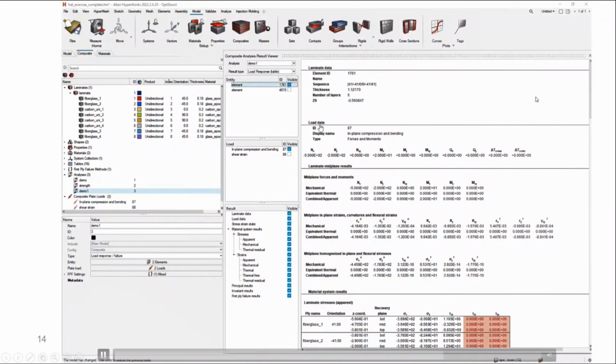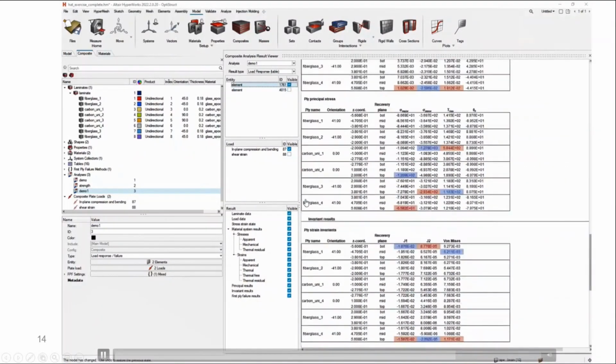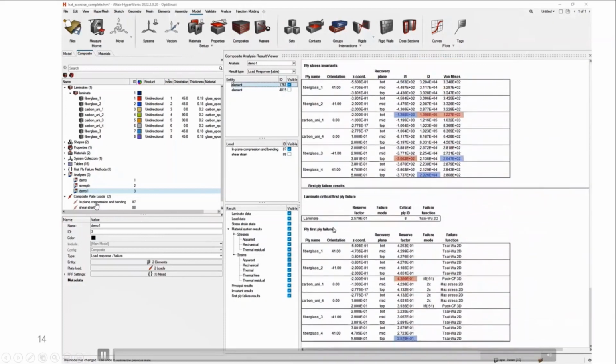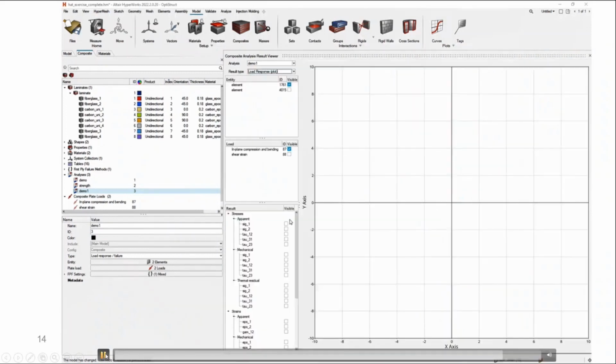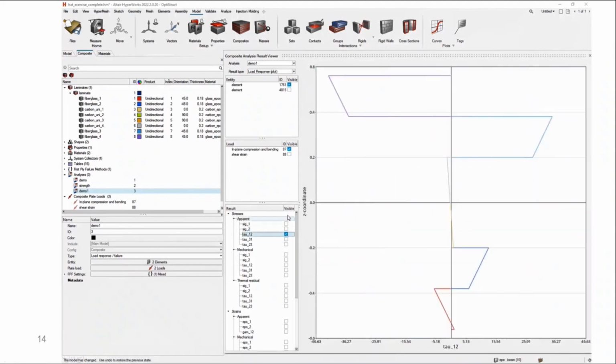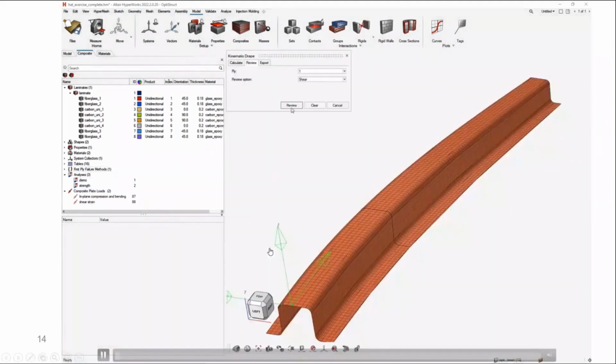So, well, a 6 degree change in some of the areas. And with the given load that I've defined here, so that's a predefined composite plate load, we can actually see that the reserve factor is basically less than half of what we had before. So there can be significant influence of the draping data towards your results. Yeah, and that was just the first quick feature.